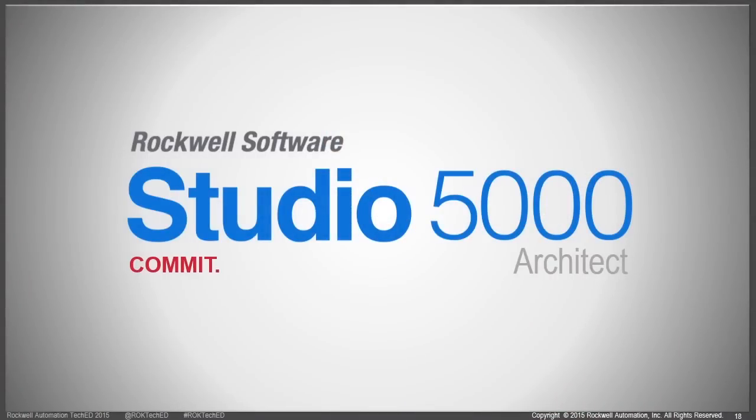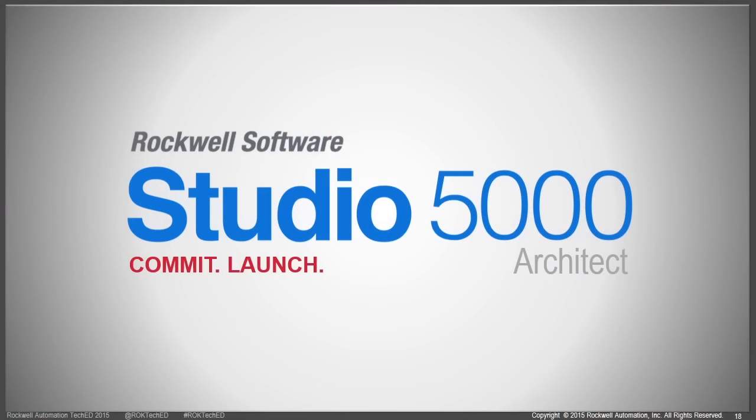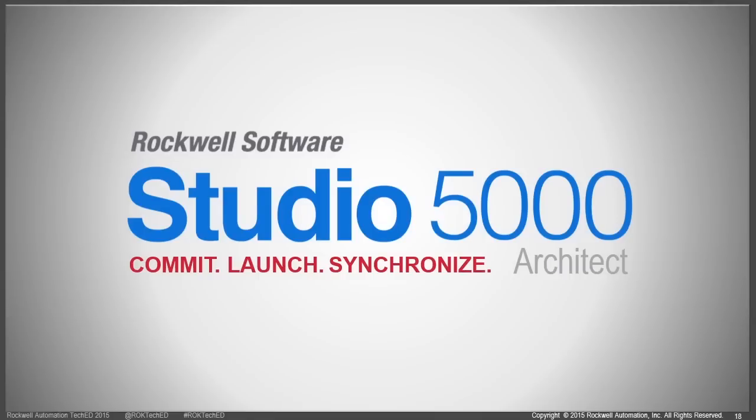So the three things that you could really do, as an example, is number one, create your system layout and use the commit process to create your project files. Number two, once you've done that commit, you can now launch into the individual designers from this layout. And number three, you can then use the synchronize process to update your architect project. Commit, launch, synchronize. This is coming out later this summer as part of V27's release. I think this is a solid step forward into increasing automation productivity. I think we're going to move on to our next question and see what other help we can provide.